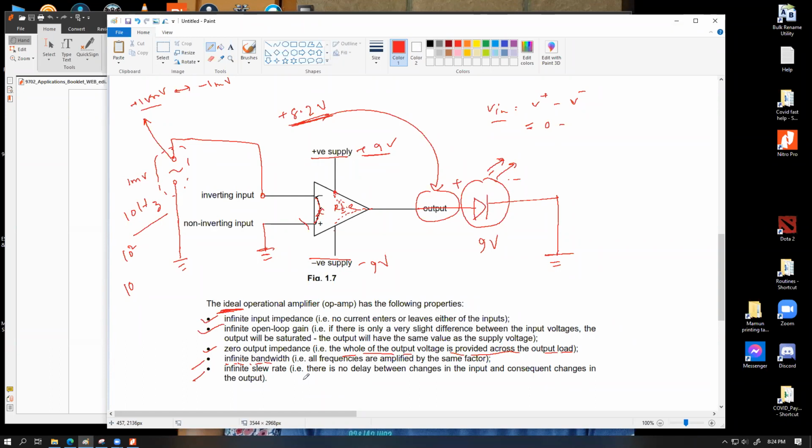An ideal op amp has zero reaction time. What could this possibly mean? It means it is converting from input to output within a negligible time duration. Exactly. An ideal op amp, which is obviously a hypothetical idea, has infinite slew rate. It means it has no delay between the change on the input side and the available change on the output side. It will be instantaneous.